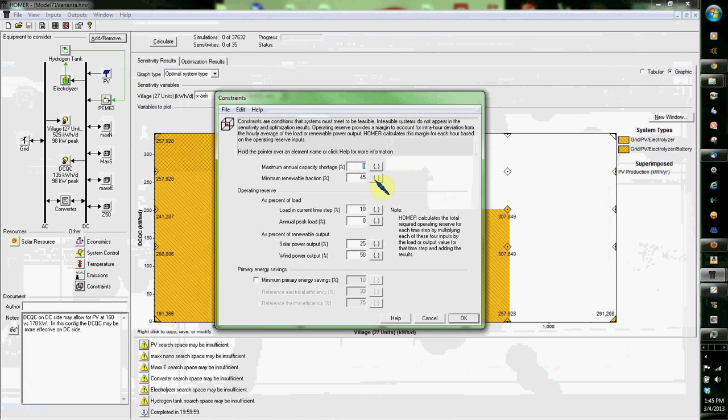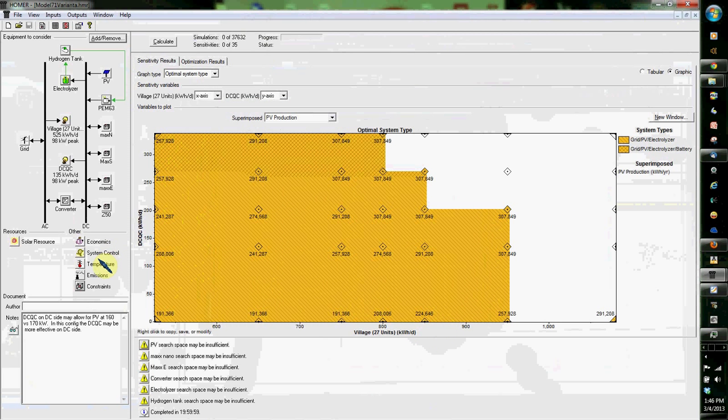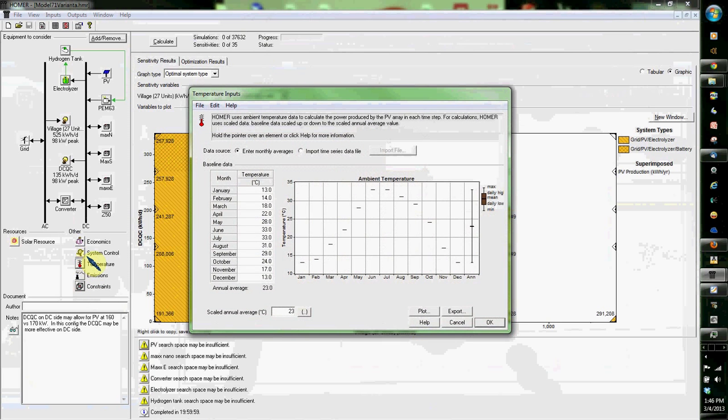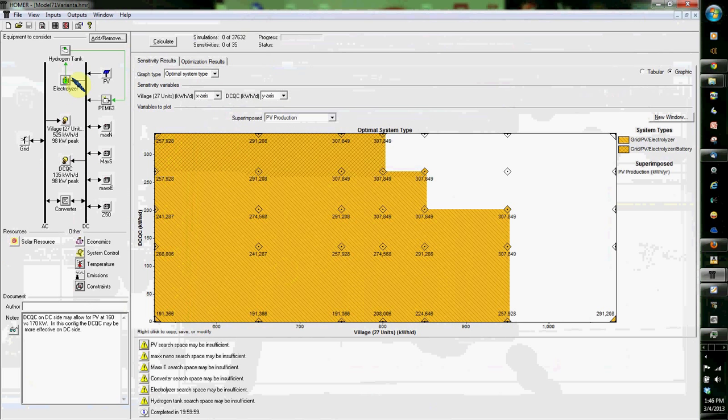And again, over here we had the constraints. I put in different constraints originally. Like I said, it was kind of rough to find my way, but with the simulation it was really a lot nicer. Temperature only in Celsius. I had originally pulled off what turned out to be Fahrenheit and didn't catch it, and so a portion of my runs were all in Fahrenheit, and for some reason I need a whole lot more solar, and my other stuff is burning out a lot faster, so beware of that. That's important to know.